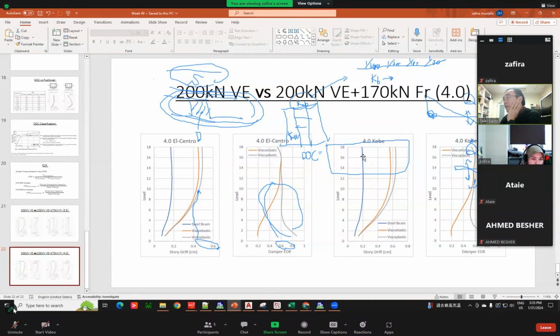And even if you have a damper, there is a damper hysteresis, and you can assume some equivalent stiffness for the viscoelastic damper. So you can adapt this equivalent stiffness in this formula. Yeah, so first you must evaluate the degree of coupling by some mathematical formula. Okay. And by changing KB, you can approximately evaluate the degree of coupling after putting in the damper. Okay.